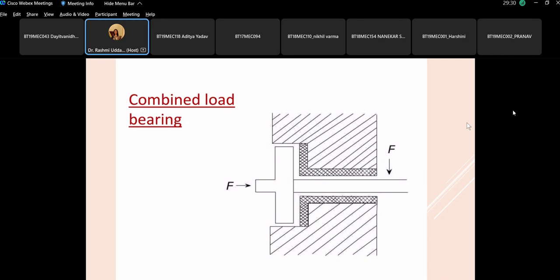Harshil, how did we compensate for zero bending moment? By reducing the maximum shear stress to 40 MPa from 75 MPa. So we know that the shaft is subjected to bending, but you can find the bending moment or the bending stress only when the length of the shaft is known, and that is the length between the bearings. When we solve the assembly problem, the location of the right hand side bearing and the left hand side bearing on the shaft and the distance between the two bearings will be known. Then we'll be designing the shaft based on bending.